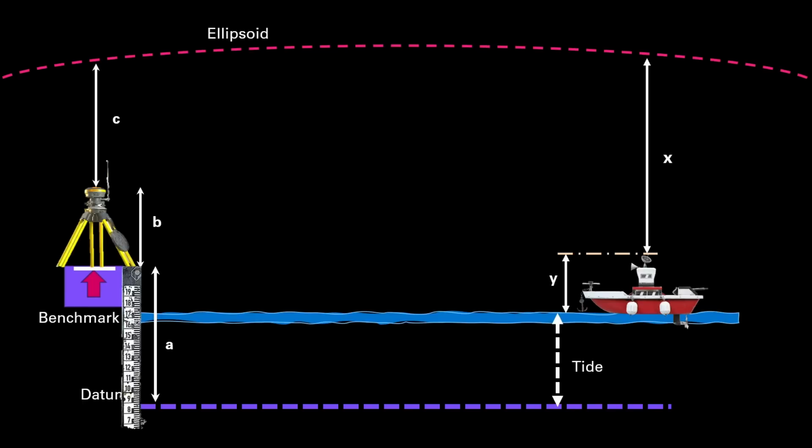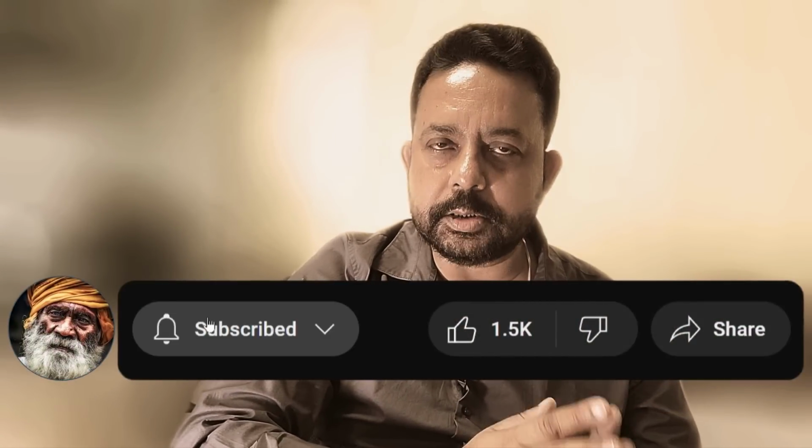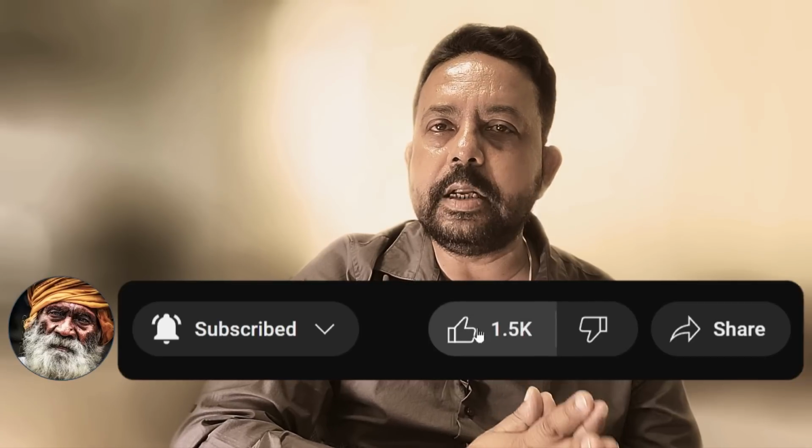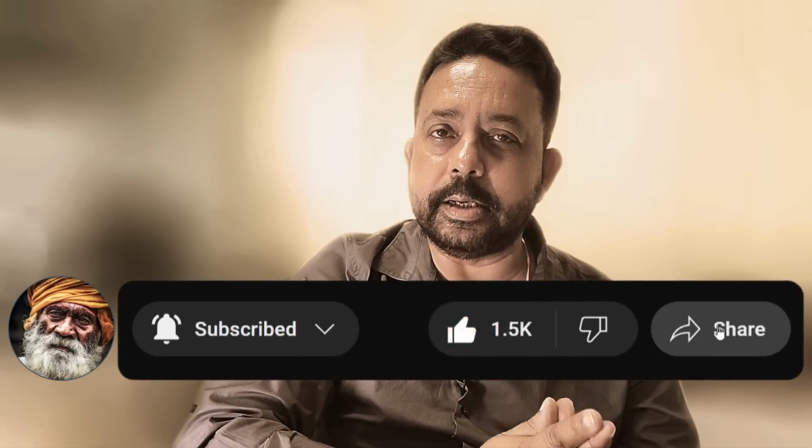And in the boat itself, I recommend you use a measuring tape every day to find the height from your antenna to the sea surface. See, we are talking about a couple of centimeters of error in tidal height. Just ask yourself, will a couple of centimeters in tidal height really matter? At what depth are you doing the measurements? Will that couple of centimeters make any difference to your depth observation or not?